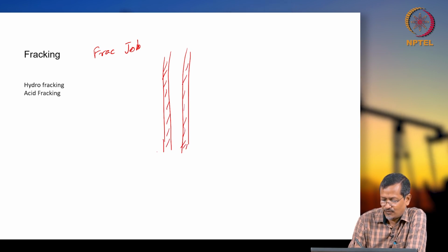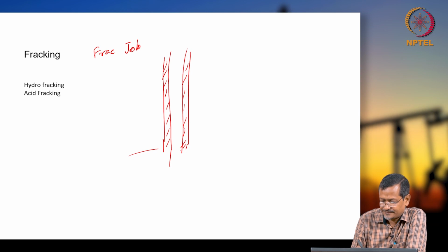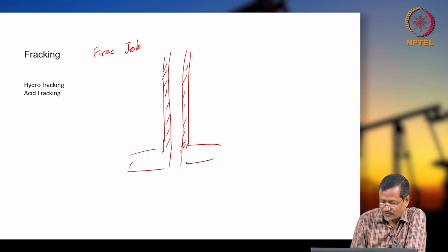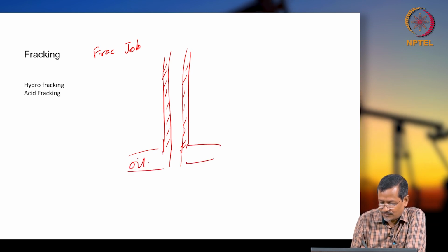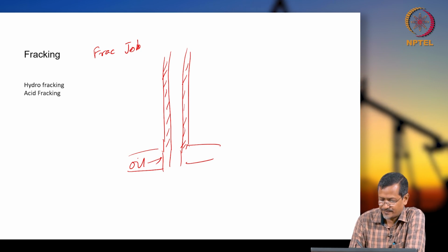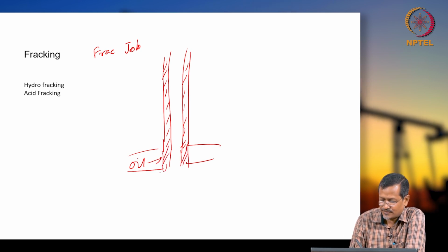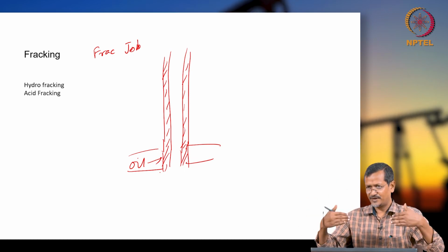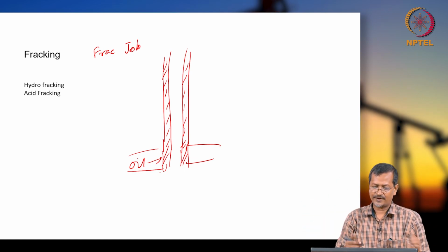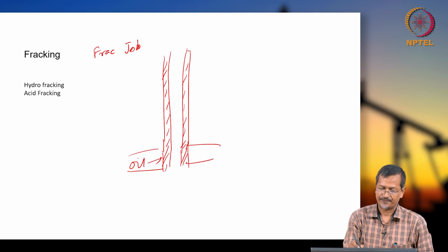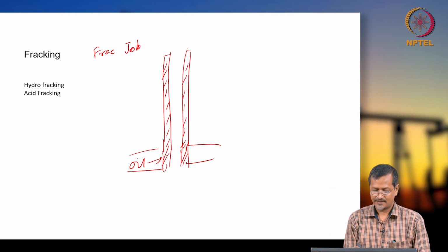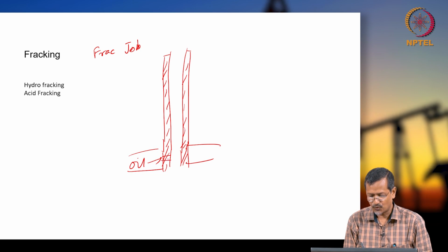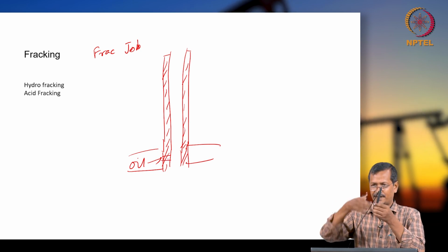Okay. Now, if I have a reservoir here, reservoir oil is there, oil or gas or water may be there, and I cemented. So, one metal pipe, I put cement, so there will be no inflow. Inflow means fluid is not entering into the wellbore and it is not coming to the surface. So, then how to get the oil? You have to put lots of holes in the cemented area. So, you put a pipe, you put lots of holes.